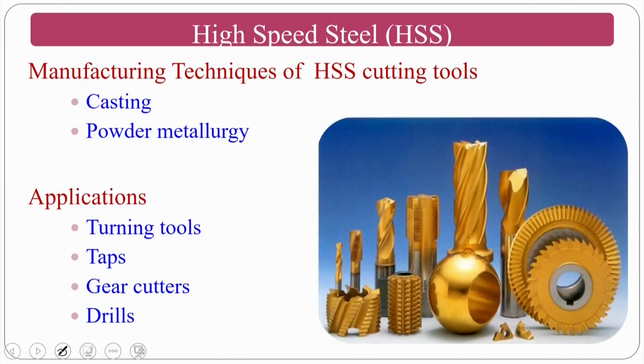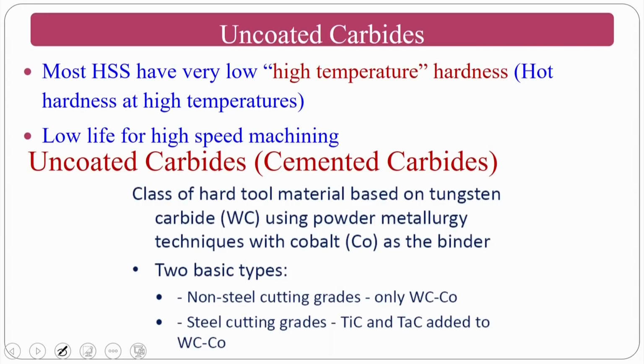So, another one is, normally these are manufactured by casting and powder metallurgy technique. The applications can be turning tools, taps, gear cutting, drills and all those things. Okay. So, we are going for the uncoated carbides.